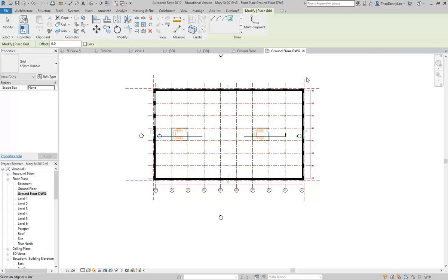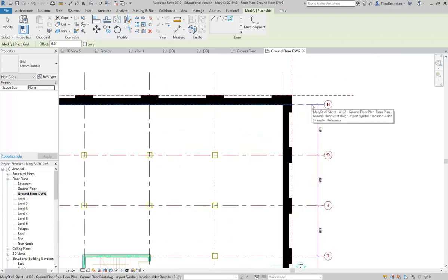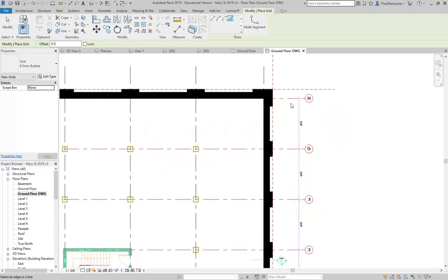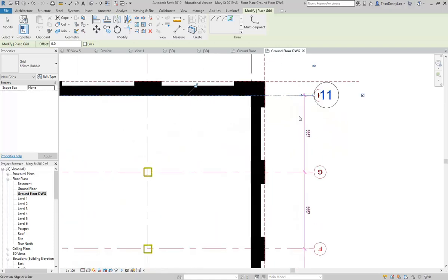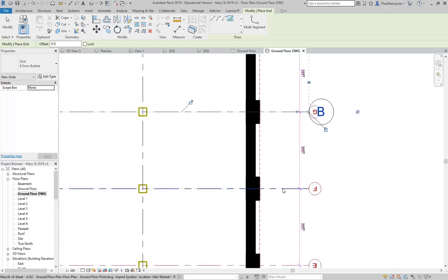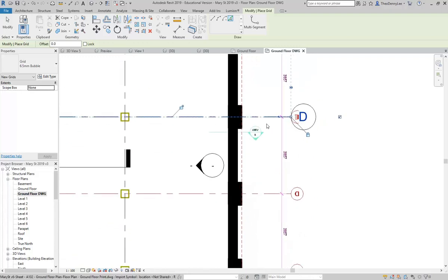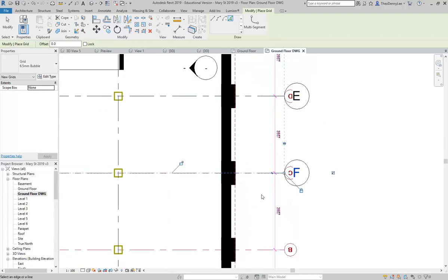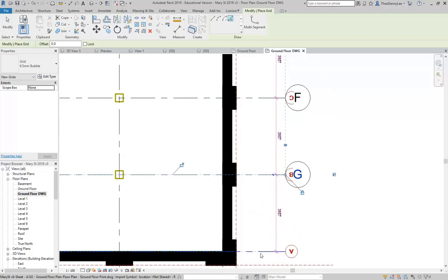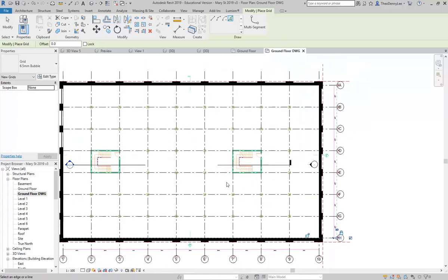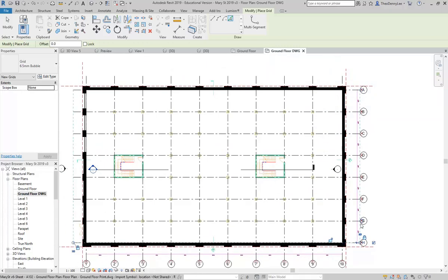Now left to right, the way you read, and then top to bottom, the way you read. But when you do the horizontal ones, start at the top, and then before you pick the next one, make sure you change that to an A, and then when you pick the next one, it'll be a B, and then you can just keep picking them like that and get letters down the side. Okay. So that way I've got A to H running down the side.